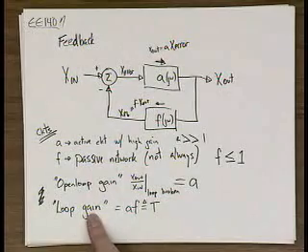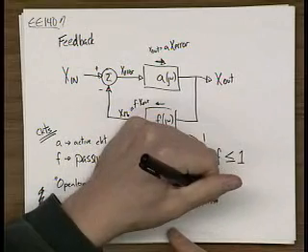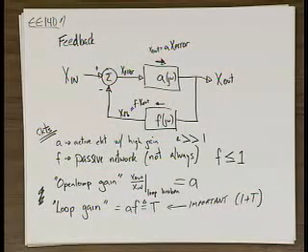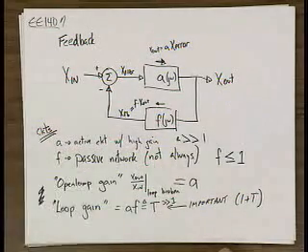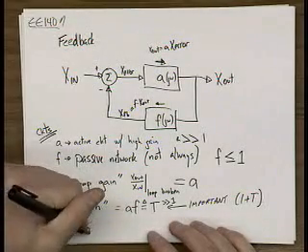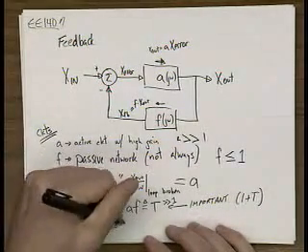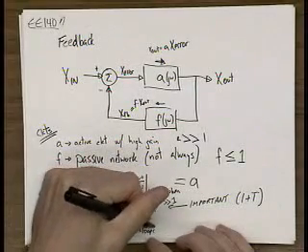So that's the definition of the loop gain. And this shows up a lot. You'll see that the term 1 plus T starts showing up just about everywhere. Okay? And obviously, and typically, in regions of interest, the loop gain is also much greater than 1. And finally, there's the closed loop gain, which is defined as X out over X in with the loop closed.